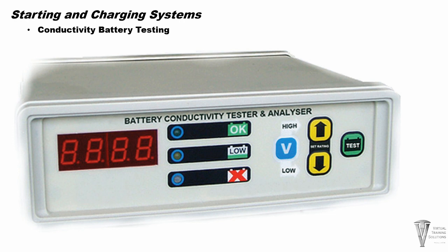Many technicians prefer conductivity tests because they find it accurately tests batteries that are not fully charged. It helps them decide quicker and more accurately if a dead battery is worth recharging or replacing. This saves the time and cost of trying to recharge a battery that is not worth recharging.